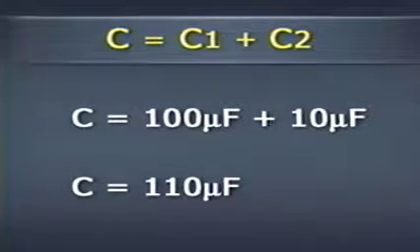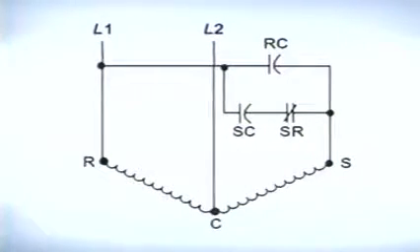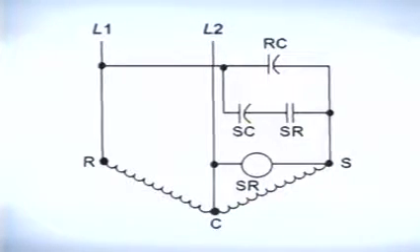In order to remove the starting capacitor from the circuit, there must be a set of electrical contacts in series with it. These contacts will open when the starting capacitor is to be removed from the circuit. If a current relay is used, remember that the contacts are normally in the open position. This set of contacts is controlled by a high-resistance coil that's wired in parallel with the start winding. This coil senses the induced voltage in the start winding and causes the normally closed contacts to open at the appropriate time. The coil and the normally closed contacts comprise a device known as a potential relay.